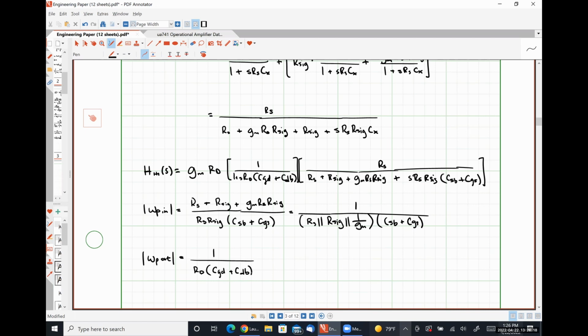So we've got our whole transfer function by doing a considerable amount of algebra here, and then looked at the transfer function in order to determine our poles, which is the order that we've been doing things previously. Okay. Now what I want to show you guys is that if we just looked at the input node, node X, and looked at node Y, and saw what resistance was connected to those nodes and what capacitance was connected to those nodes, we would literally get this exact same result, but much quicker. It's just an alternative way of looking at it. I'm trying to give you guys as many tools as possible, all right?